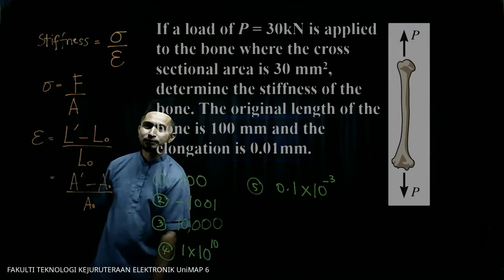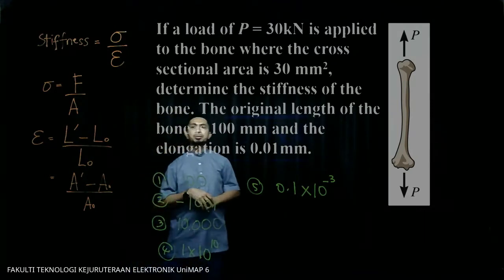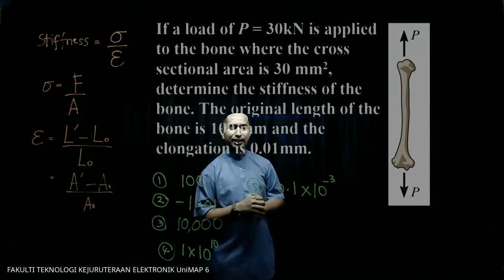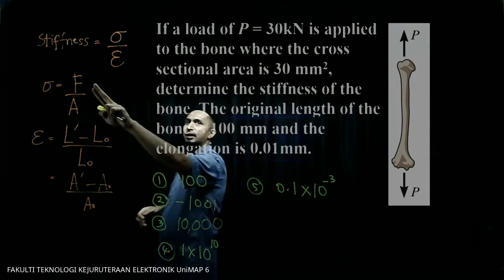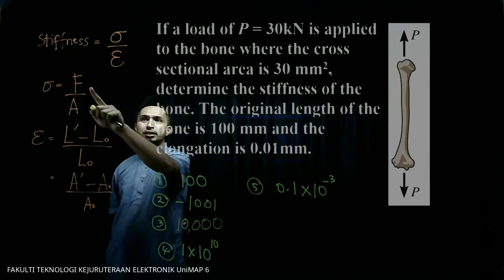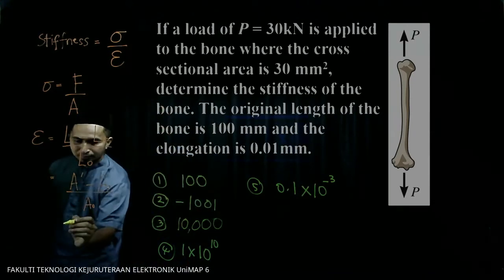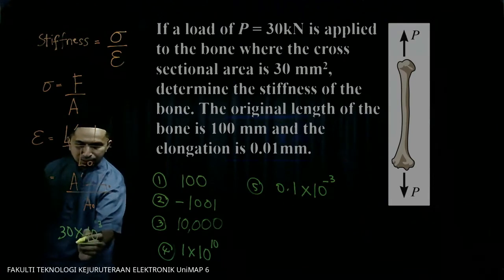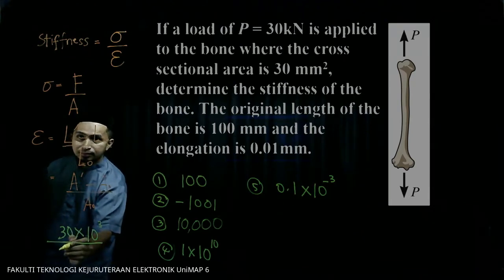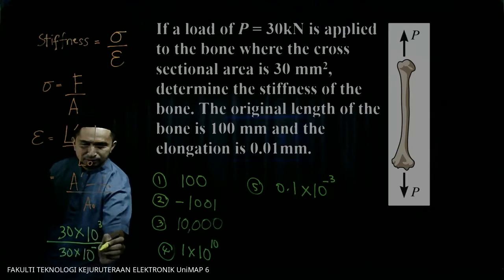So, now we have 30 millimeter square, then it will be 30 times 10 minus 6. So, force is 30 kilonewton, maksudnya 30 times 10 power of 3, divided by 30 times 10 power of minus 6.